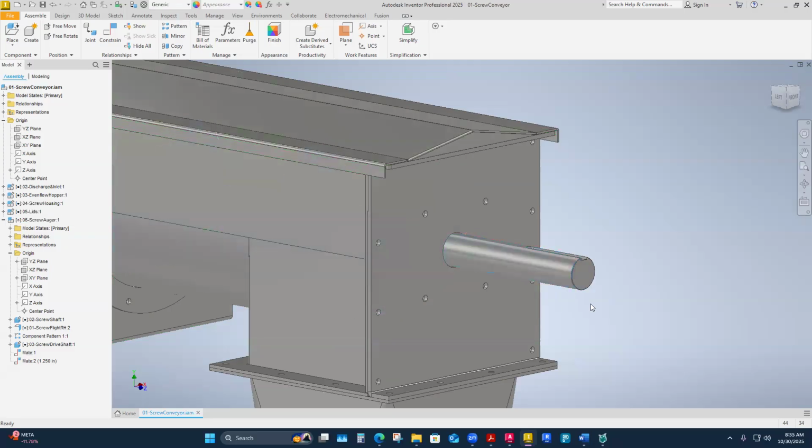And then once I knew that, which I actually found with some research and some data sheets, because the engineering for augers and screw conveyors has been done long before us, and we just have reference data to look through. Once I've sized my shaft for how big this auger is, then I'm going to go and find a bearing that's going to slip on it. And the bearing is going to come with a bunch of data sheets that says, hey, here's how big you need to make your shaft to fit our bearing accurately. And I have to know that. And then I can apply the tolerance to the shaft for my machinist and say, hey, I'm putting this bearing on it.